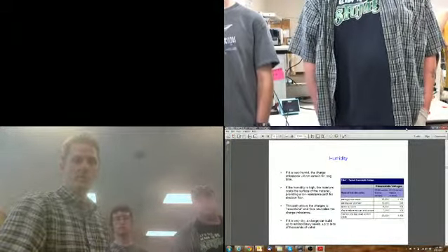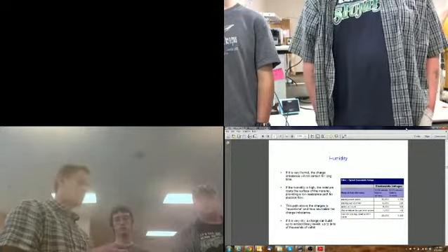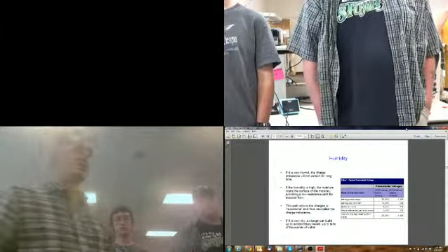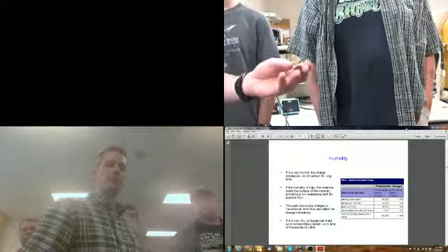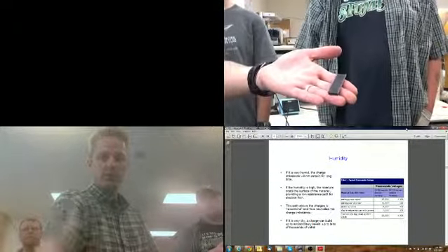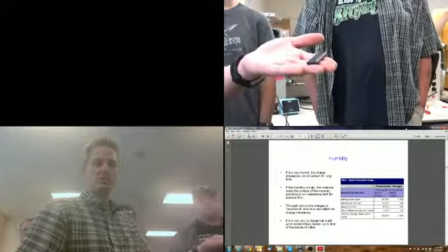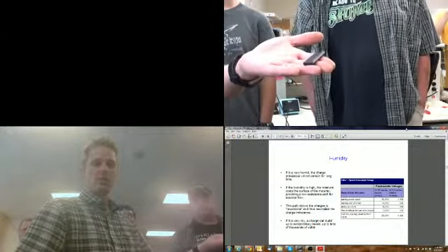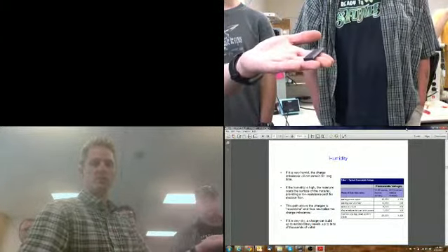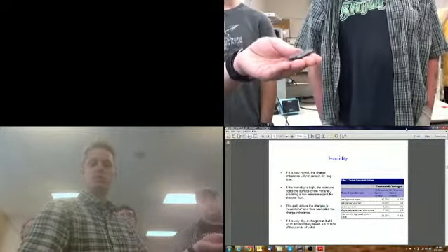Humidity has been found to discharge the electricity that comes on a component package. But it says you cannot rely on humidity. If the humidity is high, the moisture coats the surface of the material and provides a low resistance path for electron flow. This path allows the charge to recombine, thus neutralizing the charge. If it's very dry, then it's going to be more sensitive.